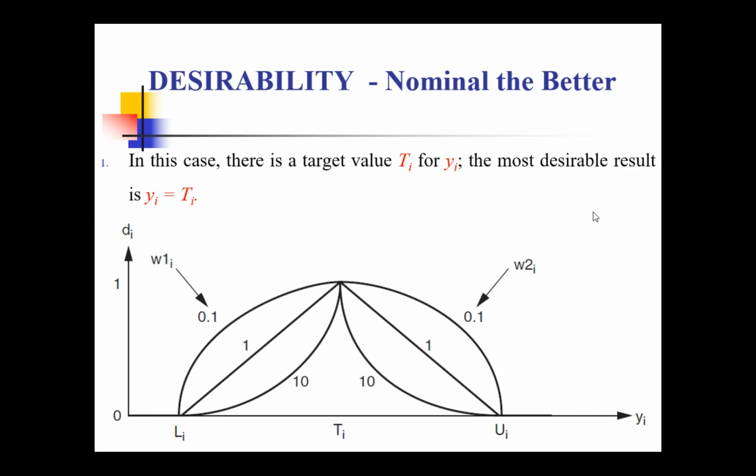Again, a major difference between the Taguchi approach and the response surface approach is that Taguchi design provides the optimal condition within the selected level values. If I consider 100, 200, 300 for cutting speed, it will tell us whether 100 is best, 200 is best or 300 is best. But what happens when the optimum condition is in between 100 and 200?